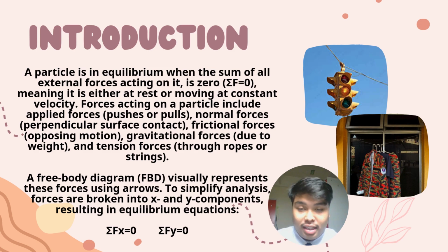First presenter, I'm Roslan. For the next slide, I will share about the introduction. A particle is in equilibrium when the sum of all external forces acting on it is zero, meaning the sum of F equals zero. So it is either at rest or moving at constant velocity. Forces acting on a particle include applied force, push or pull, normal force, perpendicular to the surface contact, frictional force, opposing motion, gravitational force due to weight, and the tension force through ropes or strings.